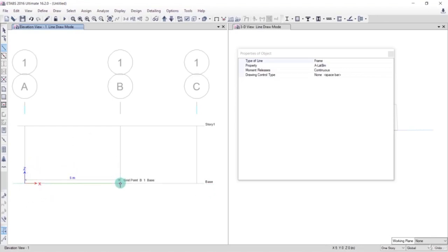So we click here, so that is of 5 meters, you can see the length, and again after that we click on here, that is of 4 meters. Okay, so your clicks should be precise. Alternatively, what you can do is that you can define grid for your load, and you can draw your beam from this point up to the load and again up to the support. Okay, so there are 2 methods, you can use any of those methods, right.